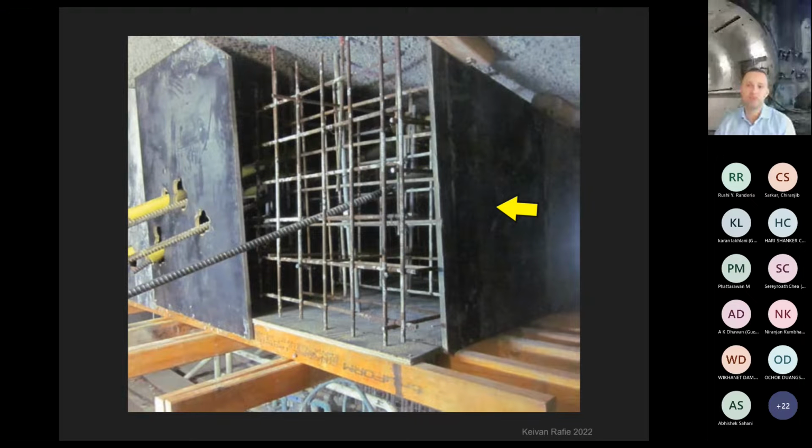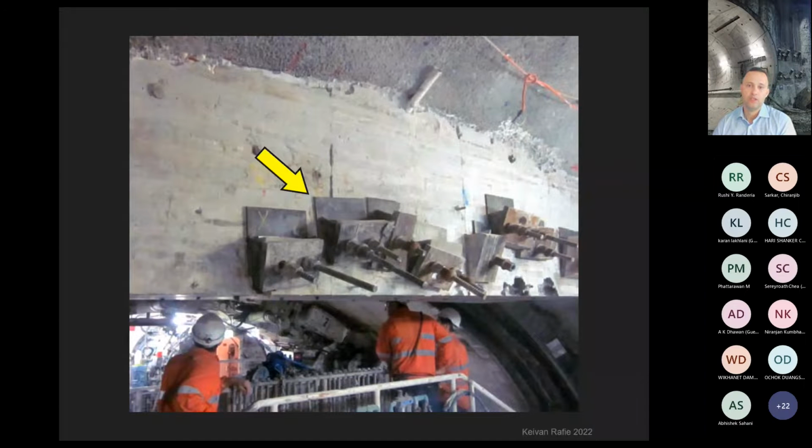This block of concrete was attached to the roof of the cavern with 12 steel bolts that were inserted deep into the rock at an angle, such that when the TBM applies force to the truss block, the block will react in tension and transfer the loads into the ground. The truss block was reinforced with rebar and poured with concrete after installation of the bolts. Later, when the concrete reached the required strength, all the bolts were pre-tensioned and tested for a minimum of 5 minutes at 100 kilonewton to verify installation quality and the anchorage in rock.